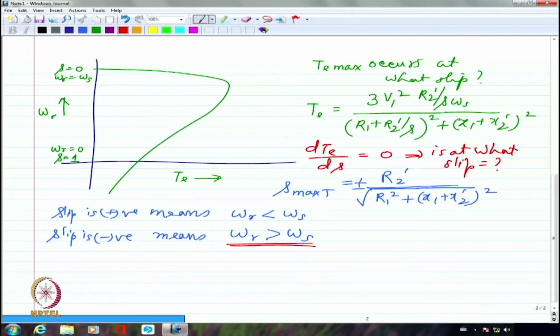So if the gravitational pull is actually acting like a prime mover, and if the speed goes beyond the rated speed or synchronous speed, that is going to cause the slip to go into the negative region. And if the slip is going into the negative region, and if I have a prime mover, in all probability, the mechanical energy will be converted into electrical energy. Right?